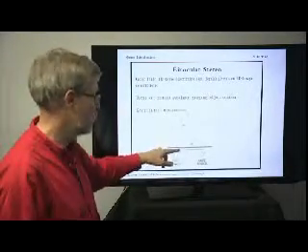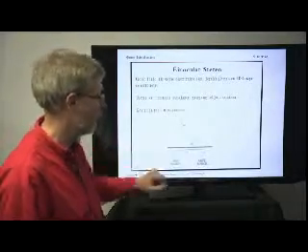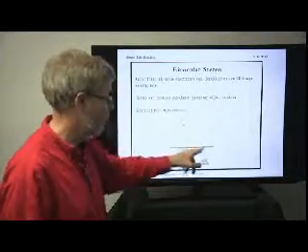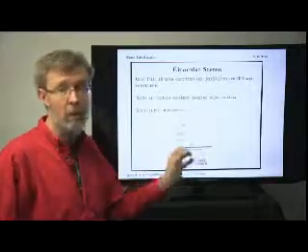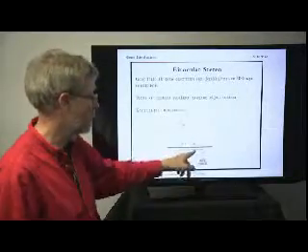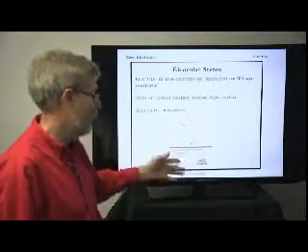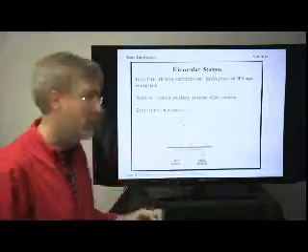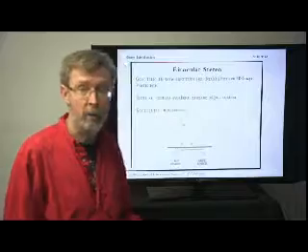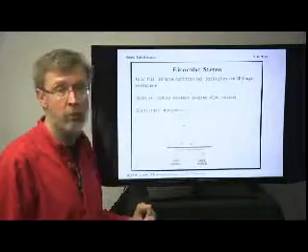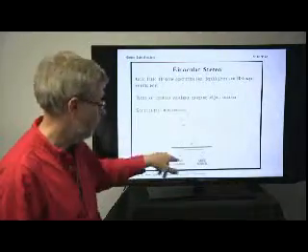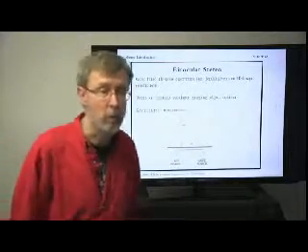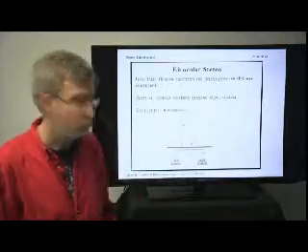And from our calibration, we can say it's out at this angle right here. Similarly, from our right sensor, we can do the same sort of calculation, only in this case the dot's in a different position, and therefore the angle is slightly different. And once we've got those two angles and this baseline, which also comes from calibration, the calculation is quite straightforward. It's just simple geometry that you can do at school. And from that, we can then calculate the position of this point in three-dimensional space.